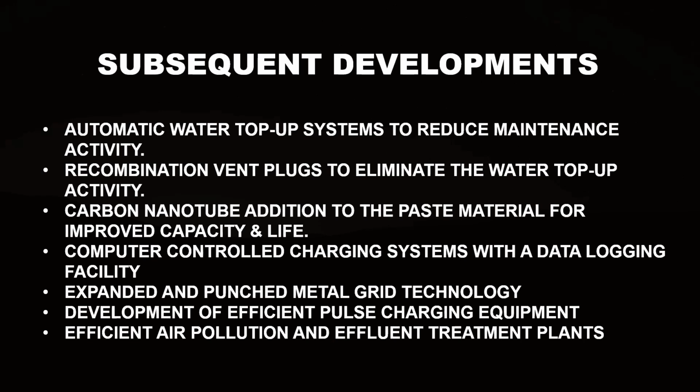This was often neglected by the customer, resulting in battery damage and reduced lifespan. To tide over this problem, automatic water top-up systems were introduced to reduce the maintenance activity. Another introduction that was made was recombination vent plugs with a special catalyst, but this did not gain much traction due to cost reasons. The addition of carbon nanotubes to the paste material for improved capacity and lifespan has also been introduced and has gained considerable acceptance.